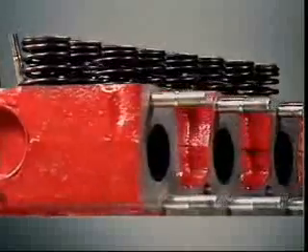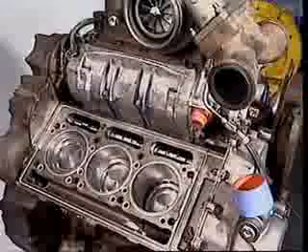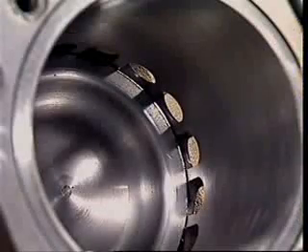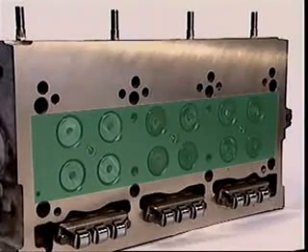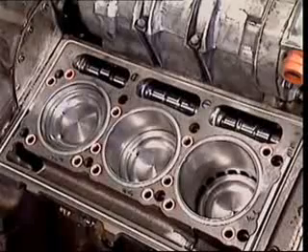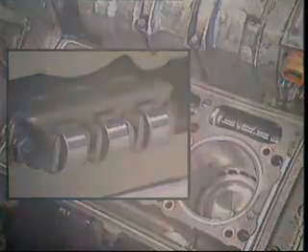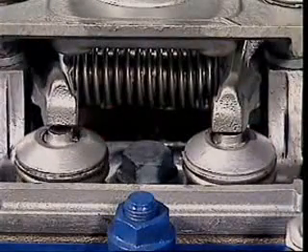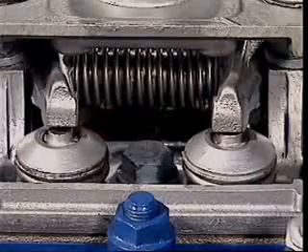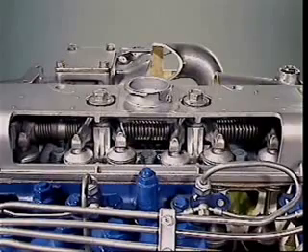Small four-stroke engines usually have two valves per cylinder, one inlet and one exhaust. This two-stroke diesel engine lets air into the cylinder through inlet ports with no inlet valves, but its exhaust ports do have valves. Four-strokes and two-strokes use the same system to control their valves. The valve is held in place by a valve guide with a spring on its stem. A rocker arm compresses and releases the valve spring so that the valve opens and closes.